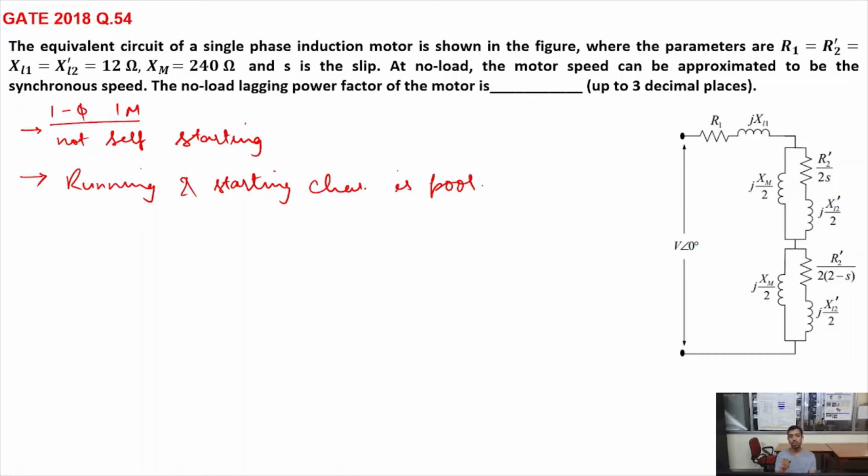But we knew from three-phase induction motor that to rotate any induction motor, we need three-phase winding. In three-phase winding, the phase difference in time and space should both be 120 degree.